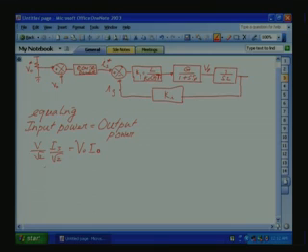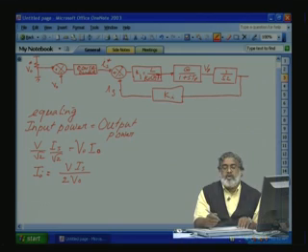From this one, I0 is equal to V IS, these are peak values, divided by 2 V0, this is the I0. So, if there is no change in load, this I0 will go to the load and the capacitor voltage will be stable. If there is a sudden change in the load, it has to be reflected. The controller should know that, and based on that it should adjust the IS so that the capacitor voltage should not change.